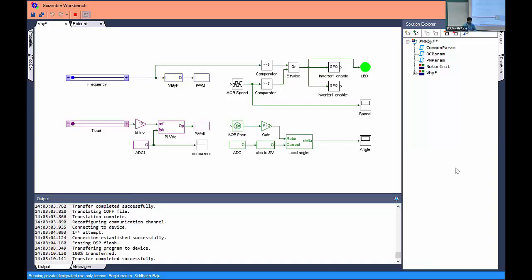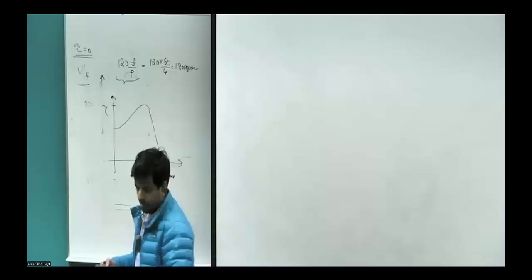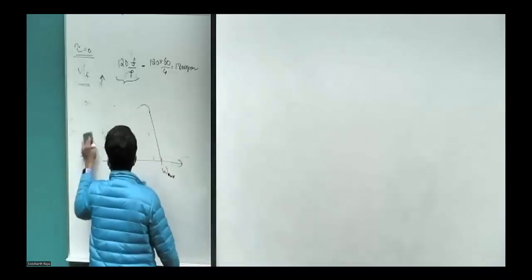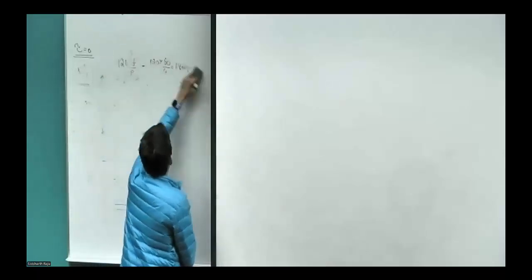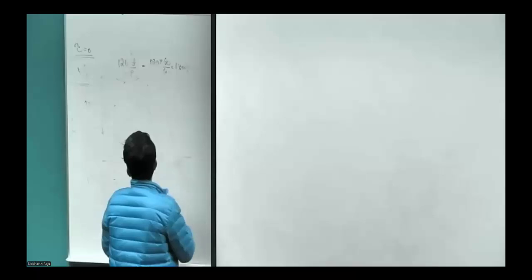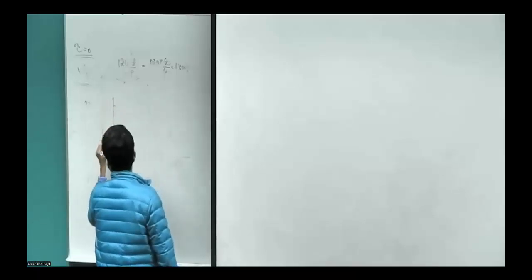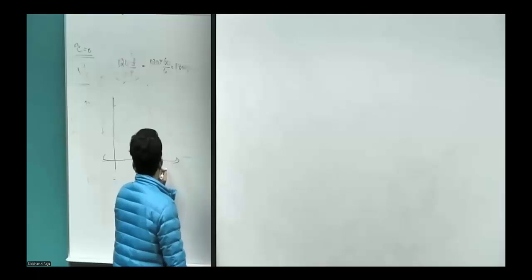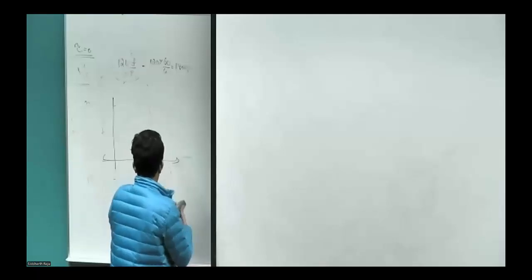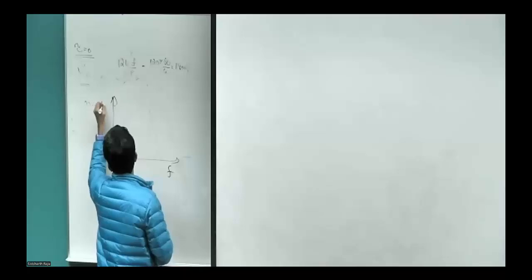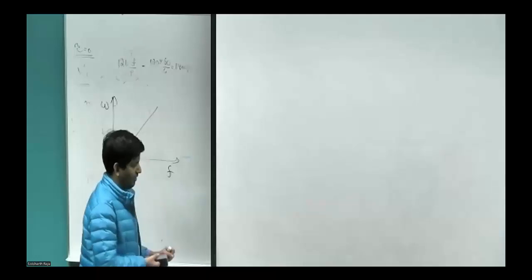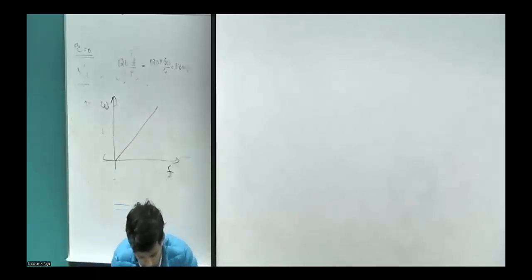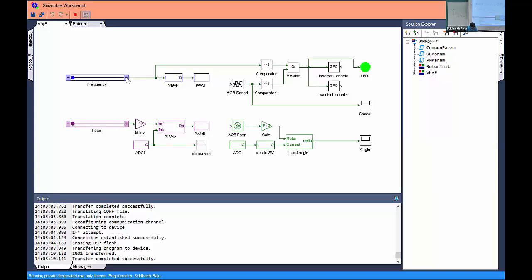Go up proportionally or? All right. So when I start increasing the frequency using the V by F rule that I mentioned earlier for a permanent magnet synchronous motor, as I increase the frequency, the speed increases linearly. Not approximately linearly, it's perfectly linear, right? So let's see if that is the case.